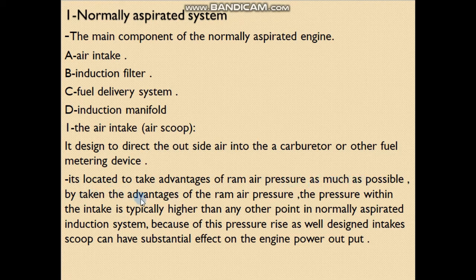By taking advantage of the ram air pressure, the pressure within the intake is typically higher than at any other point in the normally aspirated induction system. Because of this pressure rise, a well-designed intake scoop can have a substantial effect on the engine power output.